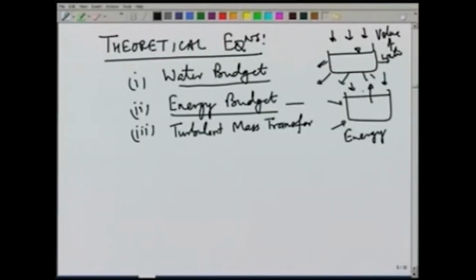What is the solar radiation which is being, let us say, radiated back or reflected back? How much is transferred to the ground, to the air? And then we can say that the remaining portion will be used for evaporation. And once we know how much energy is being used for evaporation, we can find out what is the volume of water which is being evaporated.